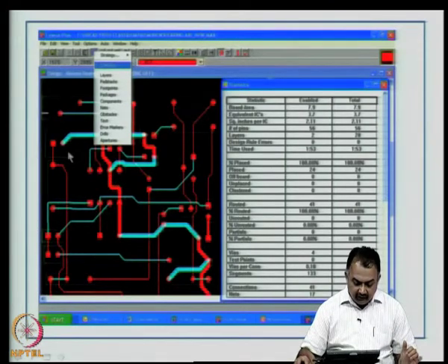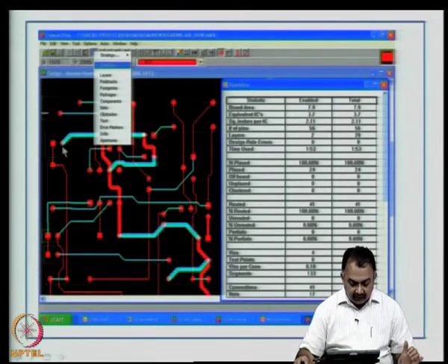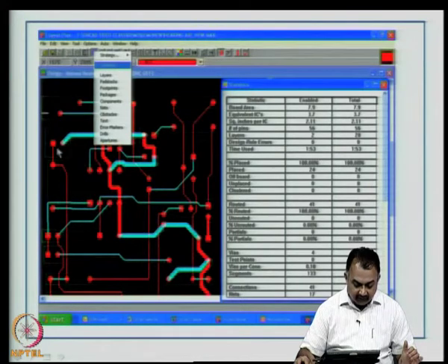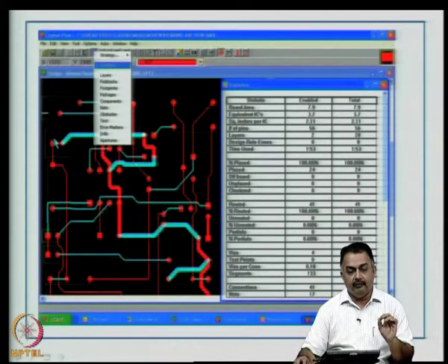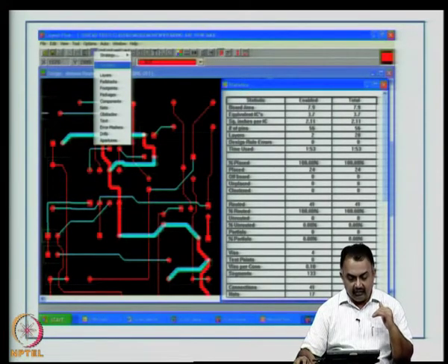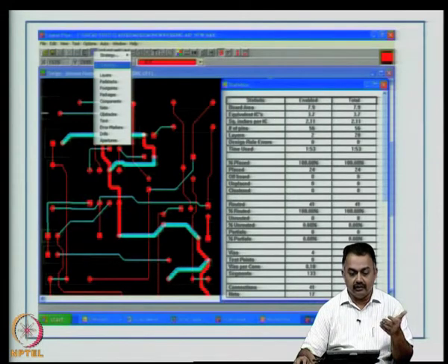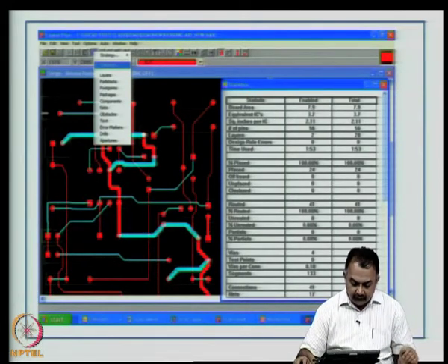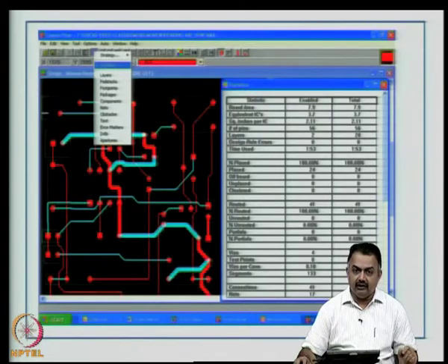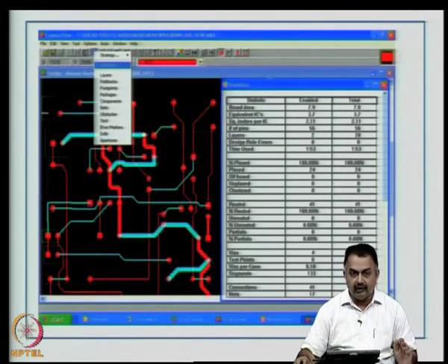Now, the interconnection between copper 1 and copper 2 is by means of a via, as you can see here. So, a via is placed in the printed circuit board, so that you can interconnect or connect layer 1 to layer 2, copper 1 to copper 2. So, the size of the via you have to very carefully select depending on the track width that you are having and the space availability and also the manufacturing capability of the manufacturer.